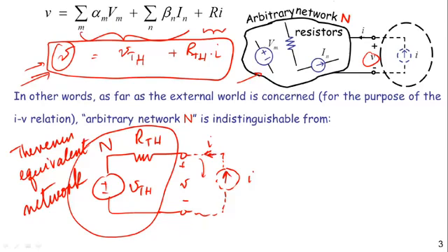In other words, using the Thevenin method, I can take an arbitrary network N, figure out a VTH and RTH that relate solely to that network's properties, and then replace that network with VTH and RTH in series. The series connection is called the Thevenin equivalent network. You will see this is another pattern, called the Thevenin pattern. In circuits and electronics courses, you will see the Thevenin pattern very often: a voltage source in series with a resistor.